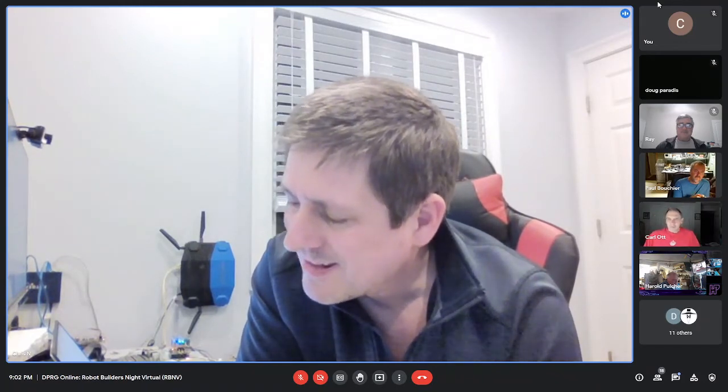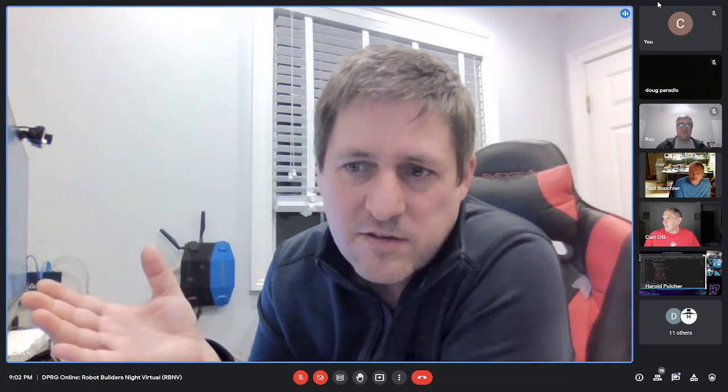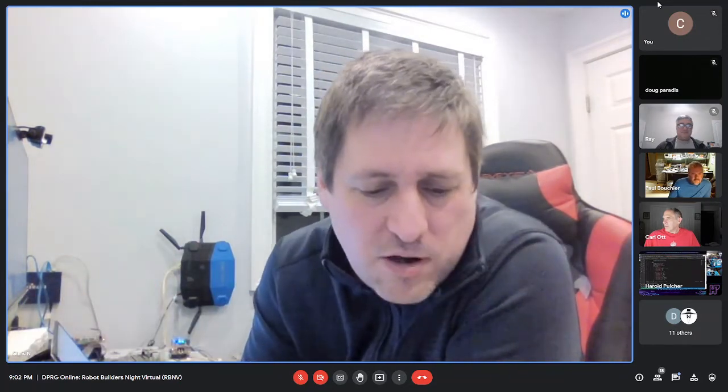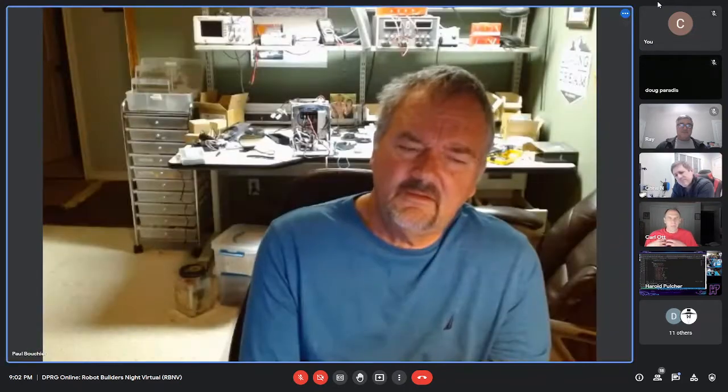Right. Now, I'm not using the standard ROS joystick node. There was one thing I didn't like about it. You had to keep pressing some other button to actively control it. And I did my own multiplexing thing, right? Because you don't want the joystick node to constantly send speed commands, because then you're constantly in interactive mode. Usually that's not what you want, but I found it annoying to have to keep pressing a button and only then can I control it. So I just didn't like a few things about it, and it was easy enough to create my own node that's just getting the joystick events from Linux, and it tells me what button or axis it is, and then I translate that into ROS velocity commands, and so I can do my own thing with the multiplexing, the way I'm doing the arbitration and all that. So I just did reinvent the wheel a little bit. But is that a PS3 gamepad?